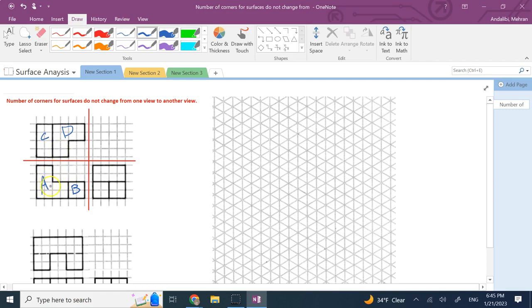And the answer is, well, A is a surface in one view, right? So in the other view, it can either be a surface or an edge. None of the surfaces would match, so it can only be an edge. And which edge? That edge should be right above A. So the only edge that matches is this small edge on the front.